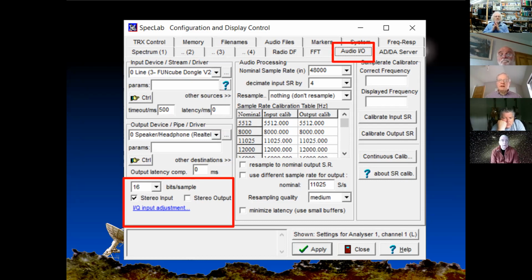these slides are taken from a system that's being fed by a software-defined radio. So we've got 2 channels of data, but they're I and Q samples, which takes us on to this point here. Over the past few years, with the advent of SDR receivers, there's an additional function that's been built in for you to adjust the gain and phase of your left and right channels inside your computer to get the best out of SDR radios.